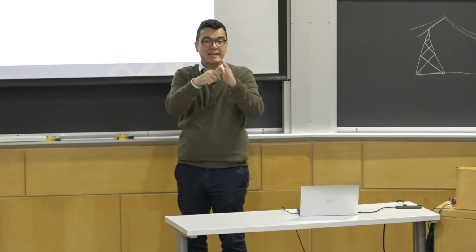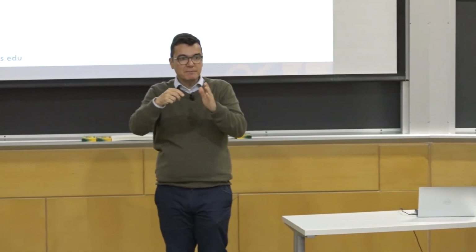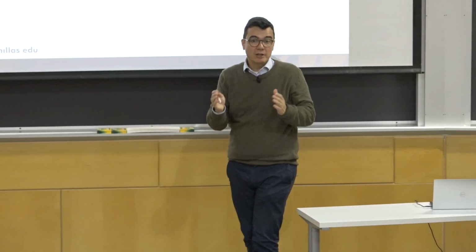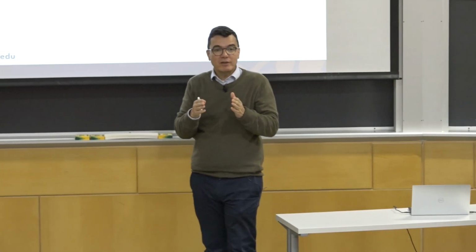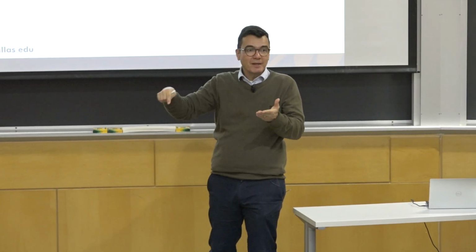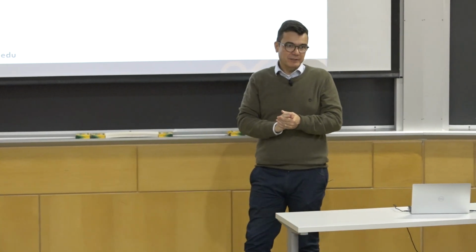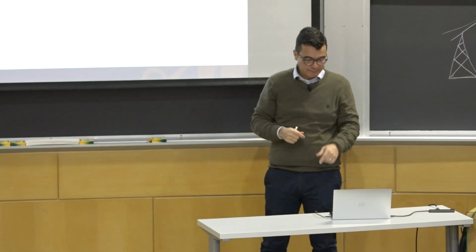It's a sine function, the sine of omega t, where omega is the frequency of the system, minus a given phi, a given angle. And every node has its own angle. In a system, you need to define the reference bus where you establish that the phase is 0. And all of them are referred to this reference, which is equivalent to saying the time where you start counting.